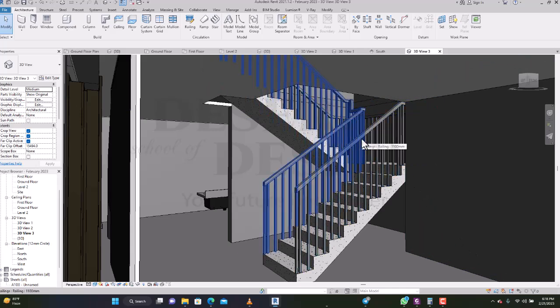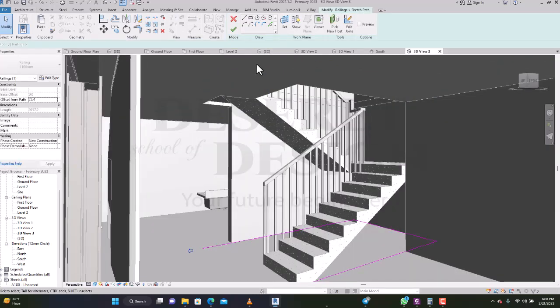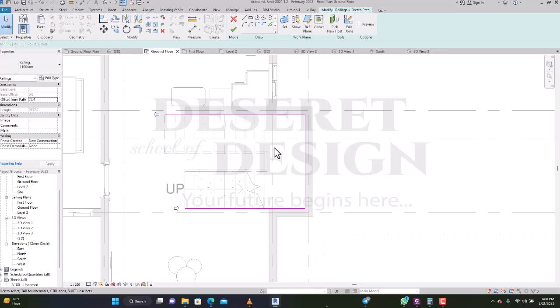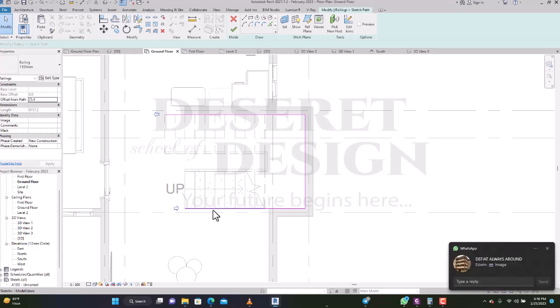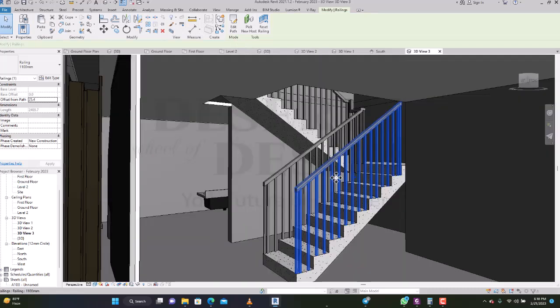Okay, so this time around you can't just straight away say you are deleting the railing. You need to edit it so that the ones you don't want, you edit it up to that place. So I can select this, then I'll say edit part, so it will open up the railing for me. Now I need the railing up to here, but here I don't need the railing. Do you get it? So I can select and delete this railing. Then I'll just accept, and that will be what will be left for this one.